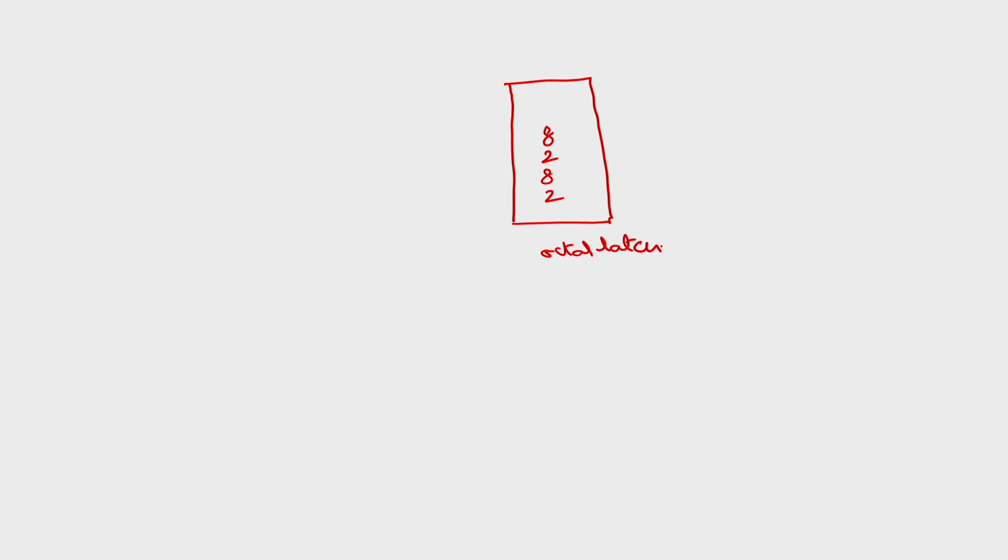As the name implies, octal, inside this there are 8 D flip flops which act as latches. I am not showing all 8 signals, so I will show these 8 signals with this symbol. This represents multiple lines, and there is a clock which is common to all the 8 flip flops. So we can use multiple latches.